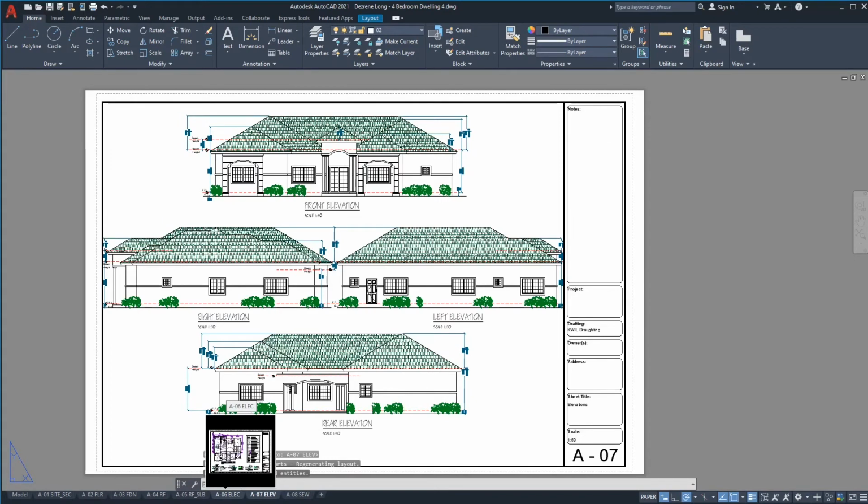So that's it. That's a very quick review on what a building plan is and the different plans that make up a building plan. You have floor plan, foundation plan, you have the roof plan, you have the electrical and drainage plan. Sometimes those plans are separate as an electrical plan or a drainage plan. You also have the elevations. You also have the sectional drawings, and you also have the details for the different aspects. You have roof details, foundation details, sewage details, etc. as needed.